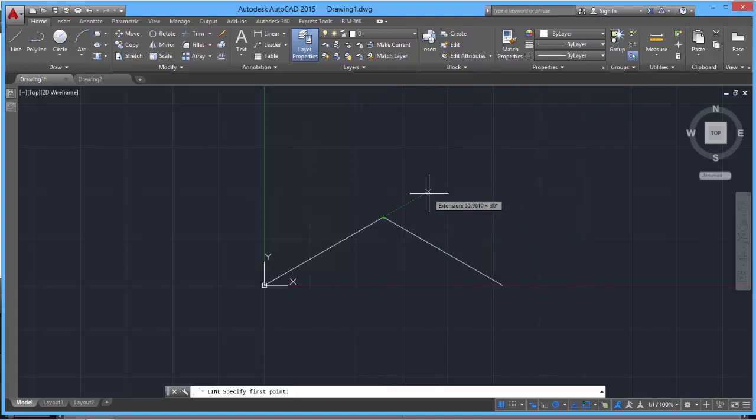If I hover over something for about half a second, it leaves behind a little green cross. I'll have that one there, I'll have this one there, I'll put that one there, and I'll put this one on the origin point. So I've got 5 of them at the moment, and they're allowing me to track and intersect points. If I want to get rid of them, I hover back over them and they disappear. Okay, so hover over to set, hover over to unset.